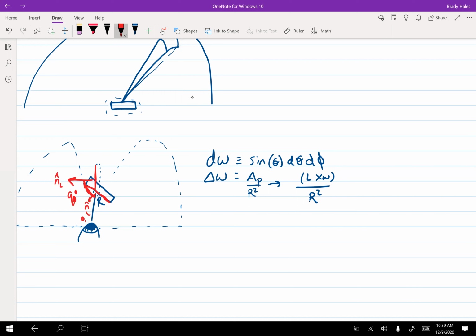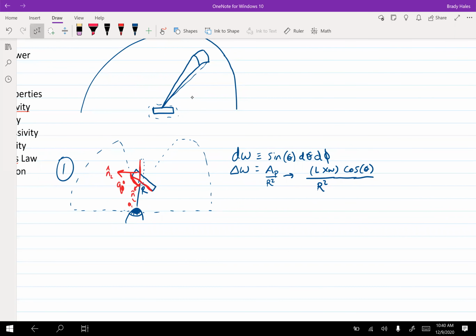No, right? So this is where for the finite solid angle for the projected area, they add a cosine theta here. And the cosine theta is that theta between the normal and the ray of irradiation. And you can see that when you're sitting directly in front of the computer screen, the theta would be 0, you see the whole computer screen. But as you rotate the computer screen, you see less and less of it, right? So hope that example helps. That's a solid angle, right?